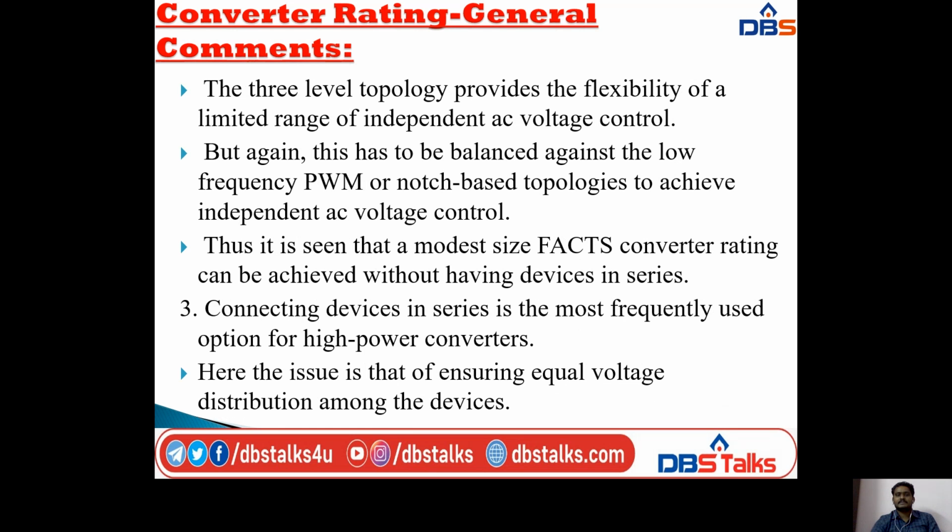Next, the 3-level topology provides the flexibility of a limited range of independent AC voltage control. But again, this has to be balanced against low frequency PWM or notch based topologies to achieve independent AC voltage control. Thus it is seen that a modest size FACTS converter rating can be achieved without having devices in series.